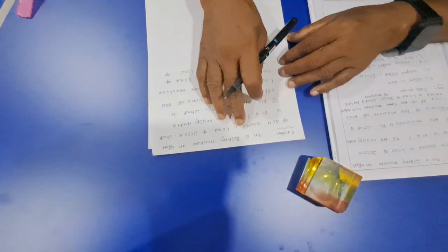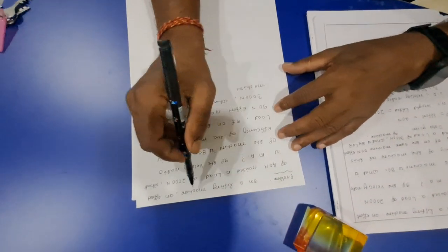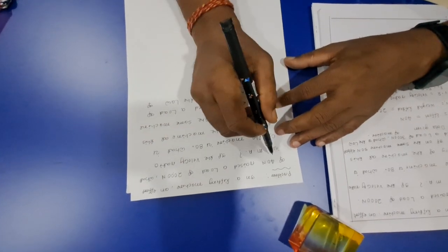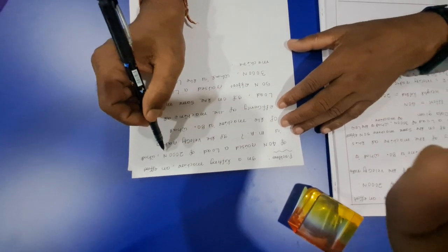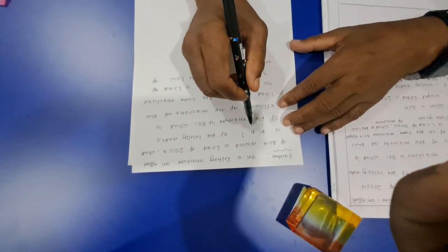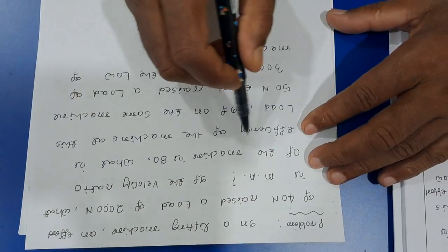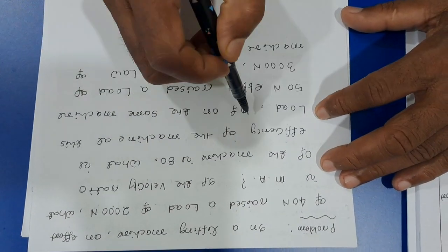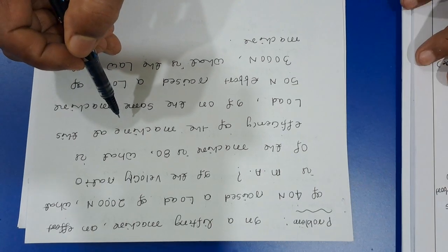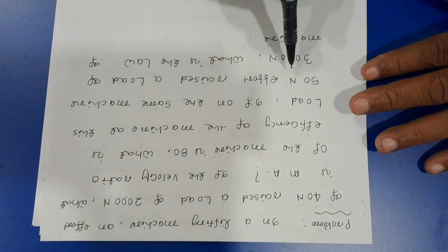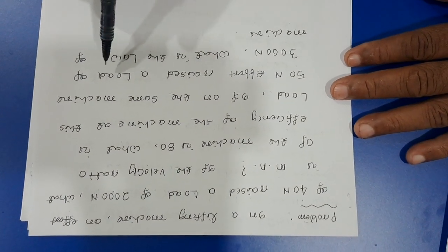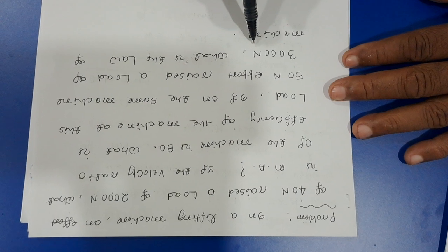Now I will solve number 4 problem. First question is like that. In a lifting machine, an effort of 40 Newton raised a load of 2000 Newton. What is the mechanical advantage? The velocity ratio of the machine is 80. What is the efficiency of the machine at this load? If on the same machine 50 Newton effort raised a load of 3000 Newton, what is the